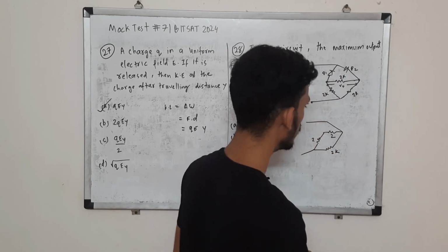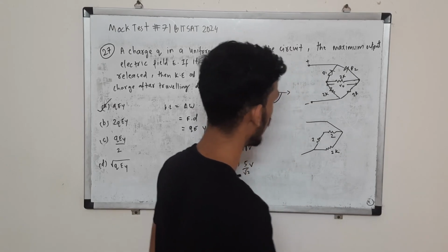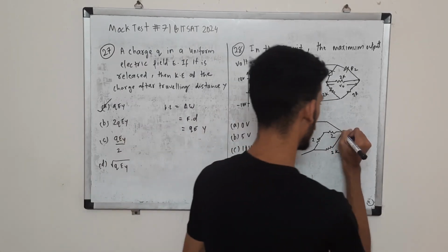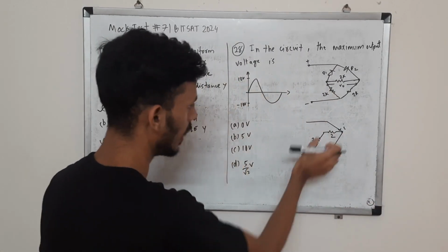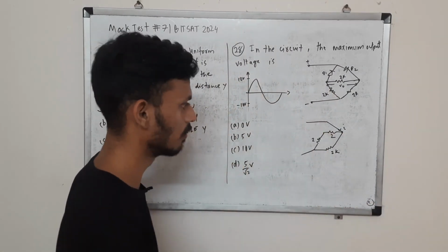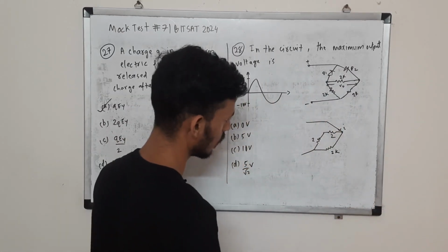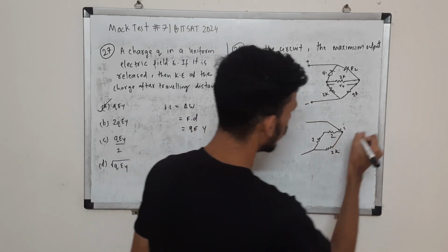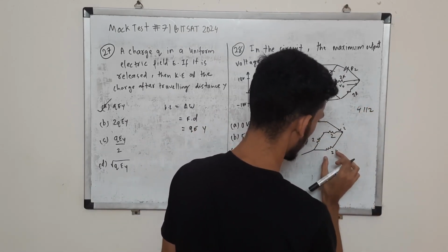So this is how the circuit looks. Now we can find the equivalent resistance that will help us find the current I arriving at this junction. Then it splits, right? There is twice the resistance over here and 1 times. So let us find the equivalent resistance first. I can see this is 4 and 2 in parallel. These two are in series and this is parallel with this.